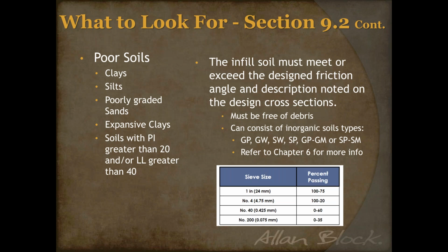We have laid out in Chapter 6 the appropriate, or allowable, infill soils. That was a previous webinar also in this series. If you want, we can send you that one as well. But we do have it laid out here, like I said, redundancy. Infill soils must meet or exceed the design friction angle, as noted in the cross section. So everything that you've designed for should be what's installed.